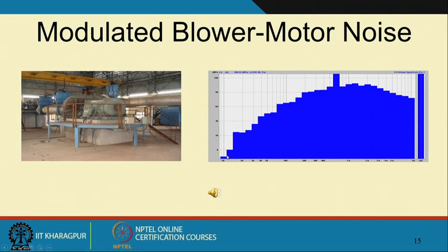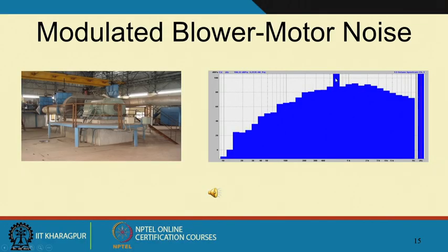And this spectrum which we have been measuring is represented in 1/3 octave bands, and predominantly this frequency is very, very loud. This is somewhere around 630 hertz, which happens to be the blower vane pass frequency, which gets modulated because of the other low frequency noises. So in any noise control or noise monitoring you do, these are the low frequency noises one has to come across.